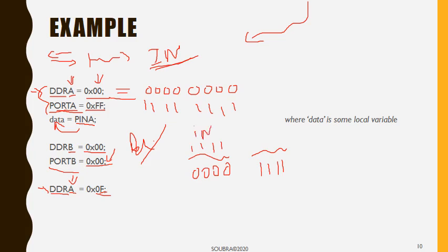What about my output? For my output, I want to drive whatever outputs I have, let's say LEDs, I want to turn them off. So I'm going to put zeros everywhere. So what should I do? What would the instruction be? Alright, so for the ins it's 1111, so this is an F. And I'm driving low all of my outputs, so this should be a 0.